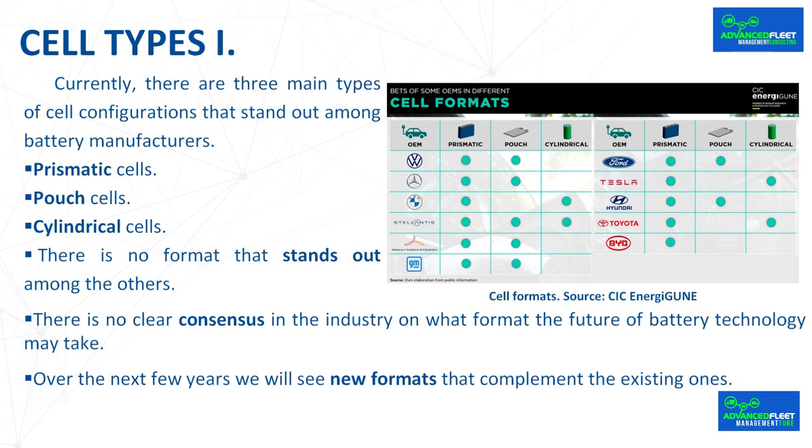The three main geometries are cylindrical, prismatic, and bag type. Each of these geometries influences the thermal dissipation, important in lithium-ion batteries, which above 60 degrees Celsius suffer degradation that produces flammable gases, which, in considerable accumulations, can lead to cell fire.